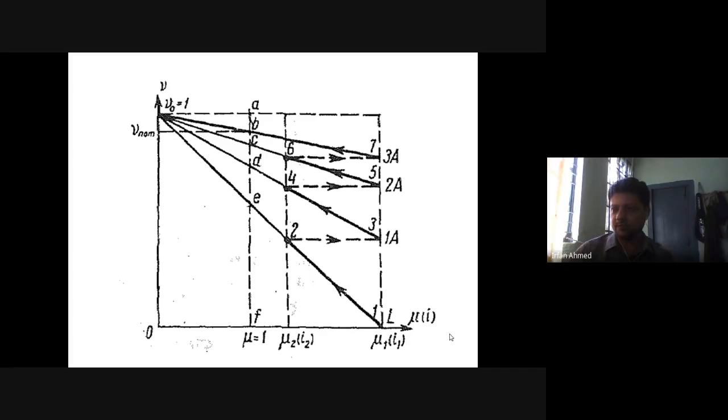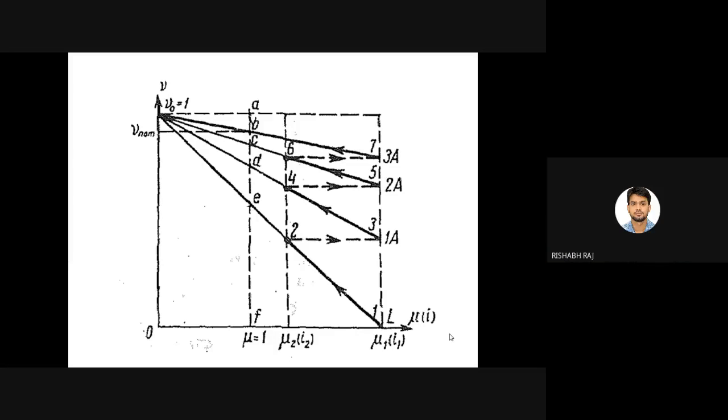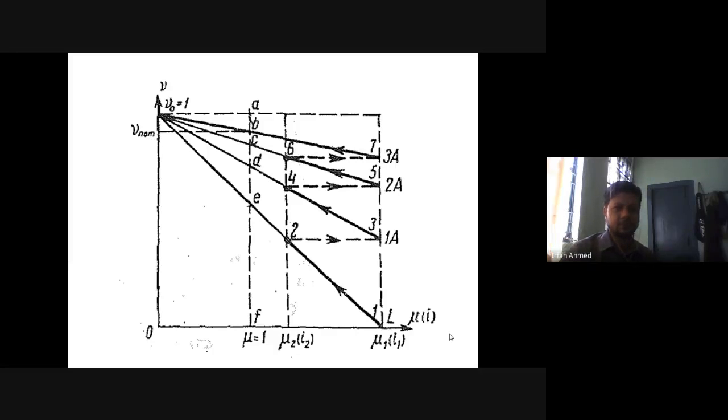In terms of absolute values, let us say the maximum permissible current is 10 ampere. So why 10 ampere? Why not 25 ampere? Depending upon the application, sir. No, your application is saying it wants this much current. This is the rated current, I is equal to I1. You have gone much beyond your application at the time of starting.